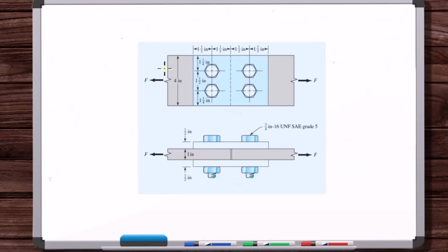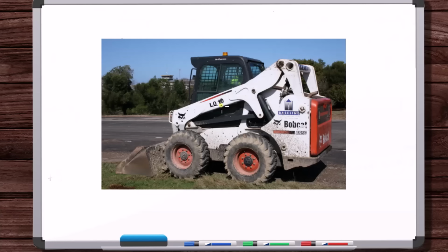Now, you might be wondering, well, it looks like here, potentially, if I applied a force like this, then these plates would rotate. I mean, maybe they wouldn't, depending on how tight the bolts are. If you come here, depending on the force you apply to this beam, these two can rotate, right? There's a degree of freedom here. This beam and this plate here can rotate with respect to one another. Okay, well, if there is potential motion that is designed to be there, it's part of the design of the piece, then that axis of motion you're not including as acting as a rigid body, right?